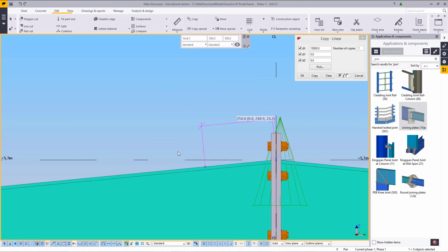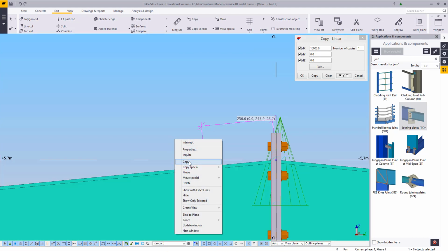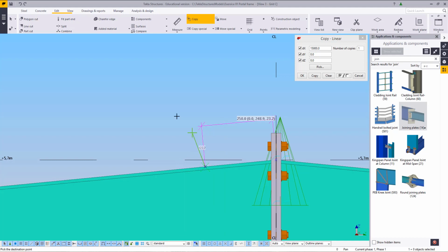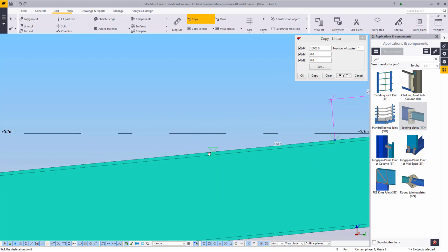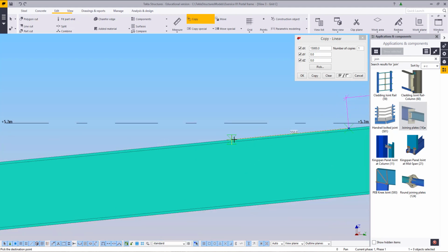we'll see that. Now, personally, what I prefer to do is selecting the point, right click copy, picking it up right on the point, and then using our nearest snap, which allows us to snap on a line. We can simply bring it out and type in 1200. Enter.